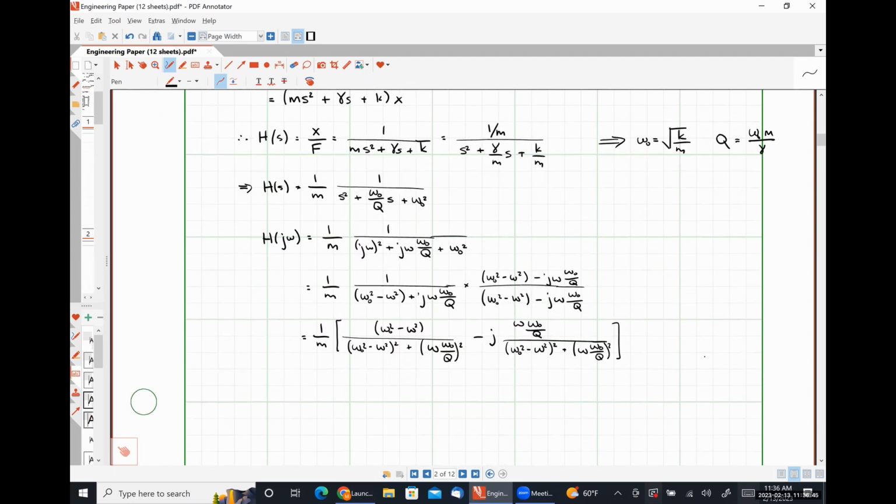So we've split this transfer function up into constituent parts. So this is generic for any simple harmonic oscillator. We have two simple harmonic oscillators, one for our drive and one for our sense. So we're going to use this same transfer function for both, but everything is going to have a subscript of D when we're looking at the drive side, and everything is going to have a subscript of S when we're looking at the sense side, okay?